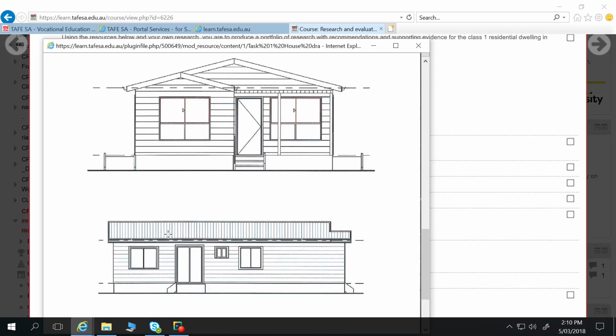We can, if so wanted, employ a hipped roof on here rather than the gable ends that we've got. We could do it as a truss roof, as a pitched roof. We could even do it as steel portal frame construction if we wish. Now, steel portal frame is the type of construction which is typically used for sheds, whereby, has everybody seen some prefabricated steel sheds before and looked at the type of framing that's used in there? I've got a few nods happening.